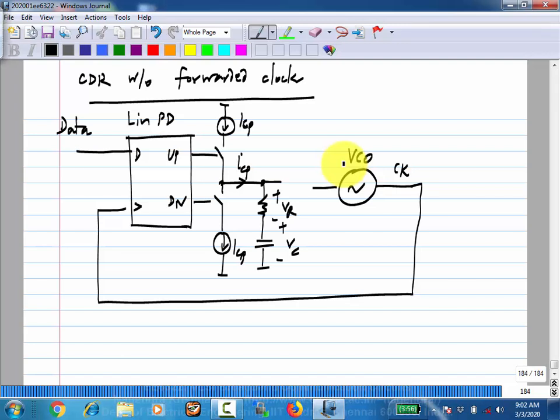Okay, the data could be jittering around and so on. So that happens because of the resistance. And even during the derivation, we concluded that the C has to be very large. Essentially, you have to reach steady state with the resistor voltage being applied to the VCO and then use the phase shift between data and clock to update the capacitor voltage. Okay? Is this fine? So now, of course, we have to do the analysis quantitatively and see how things work out.